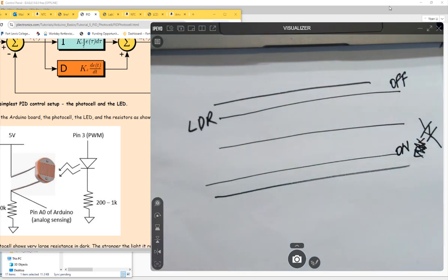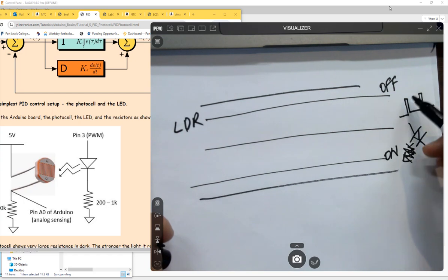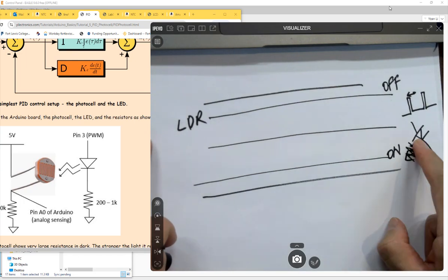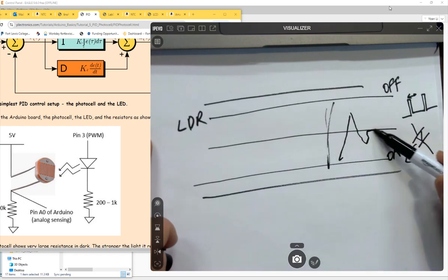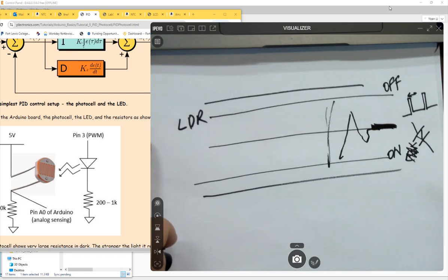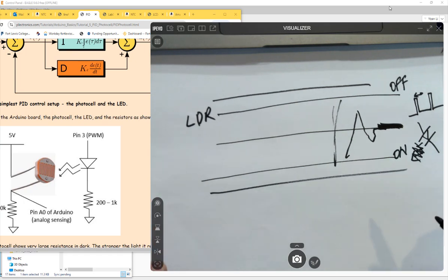Okay? So what you can do is use a PWM waveform instead of just simply turning this on and off. You can use a PWM, an adjustable duty cycle, to control the brightness of this LED and adjust it. So eventually it's not overshooting, it's not undershooting, eventually it's stabilized at this brightness by using that feedback control. That's the easiest feedback control you can apply to a microcontroller using PID. And that'll be a really good project you can talk about during interviews. Make sense? No motors, nothing else.